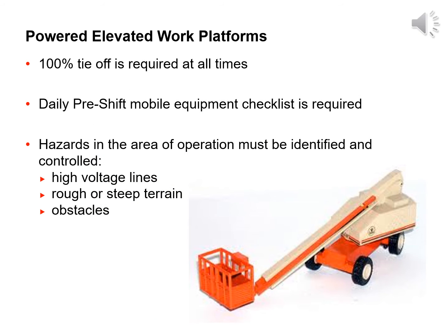When operating a powered elevated work platform, it is important to remember that 100% tie-off is required at all times. A sudden jolt has thrown people from man lifts before they could react. You should always check for overhead obstructions before driving or elevating the platform. Prior to each use, a safety inspection should be completed and documented by the operator. This should include a visual check and a function check. If a problem is found, red tag the equipment and tell your supervisor.